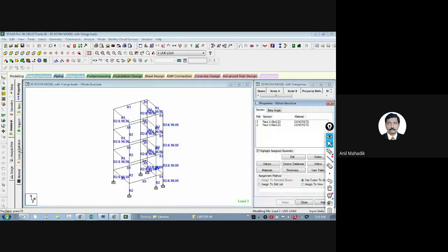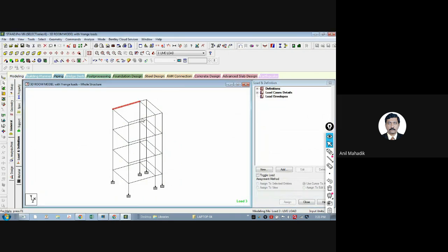Now, if I want to check the deflection of this beam, can I take this combination? For which load case or combination should I check the deflection of members like beams? Can I use this combination for checking the deflection? No, sir. So what combination do we take for deflection check? The factor will be 1 itself.